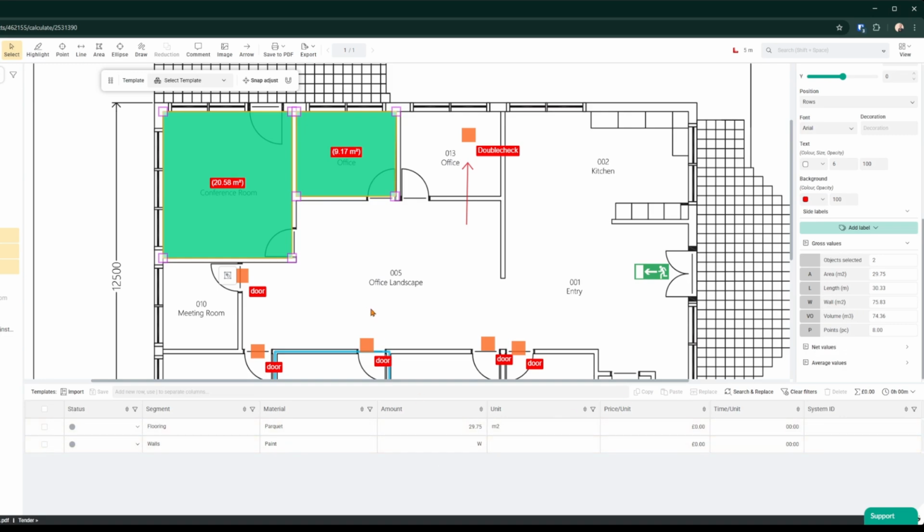And here I can go and remove with a calculation line in here. I can remove maybe the door openings. So I can type in W minus the size of the door. And I will have a smaller amount to work with, as to get us as close to a perfect estimation as possible.